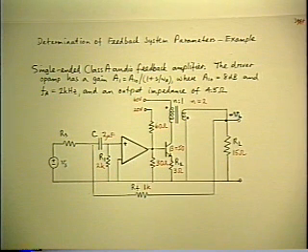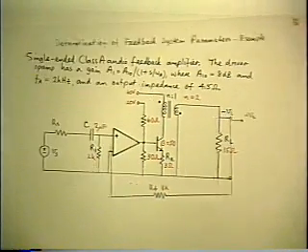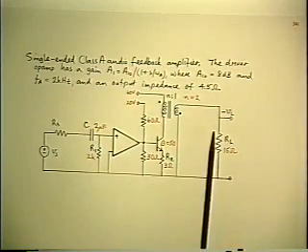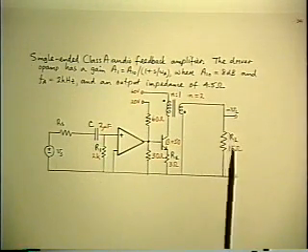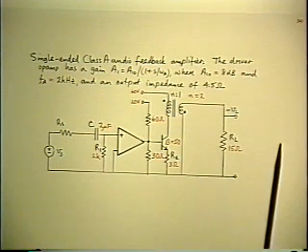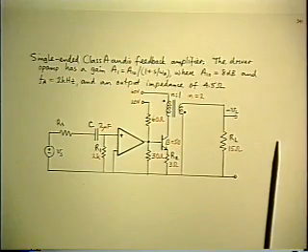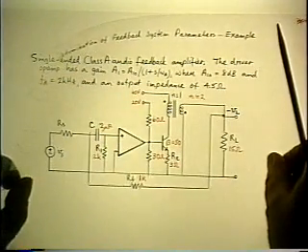Now, again, to revert to the conventional analysis, just to illustrate why you run into difficulties, the conventional approach would be to break the feedback path, calculate the forward gain, and then put it back into the closed loop. And the trouble with that is you get the wrong answer, because you've changed the value of A by taking away the feedback path.